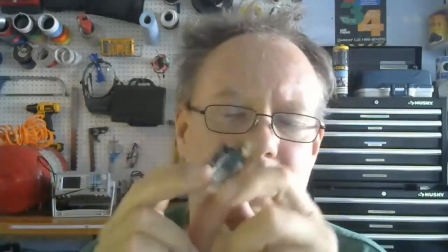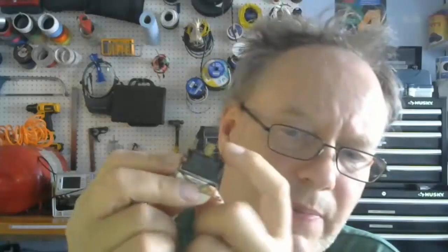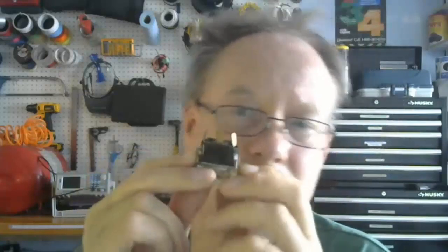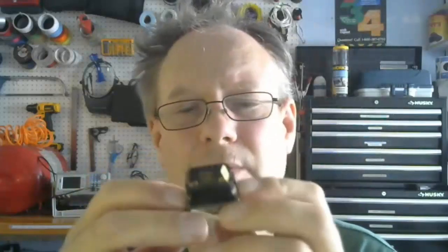But let's take a look at these contacts. Again, we're talking about the attributes of these things. We know it's a single pole double throw switch, but you see these are pretty big, right? That means you can put a lot of current through there. The signal coming from my horn wasn't a lot of current. The current going into the wipers might have been a few amps, and that's fine. This thing can handle a few amps, no problem.